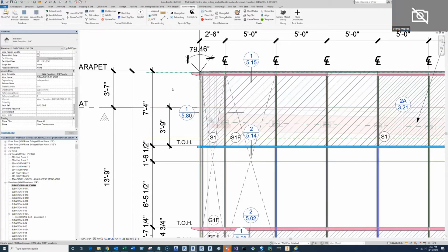The workflow I would see would be: do GG 2.0, get your glass sizes right, change your glass types to the right glass types, then run a tool relative to glass types, because backpans and shadow boxes are relative to the glass types. So there'd be 3 steps. They're not relative to the profiles in a couple places maybe, but mostly they're relative to the glass type. So get your glass sizes right. Then Alan could make a tool that says, just tell me which glass types have backpans and shadow boxes, and it could roll through and do it all for you. That's the way I would see that happening.